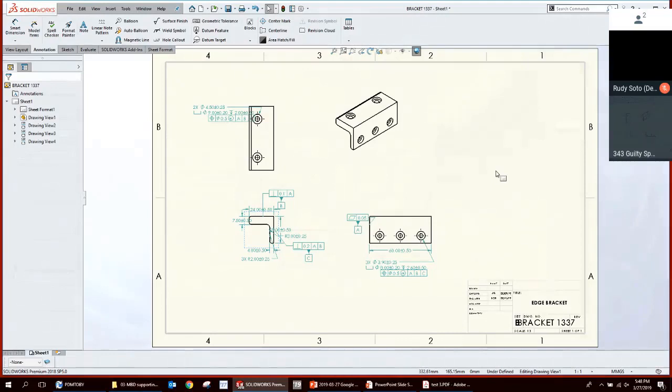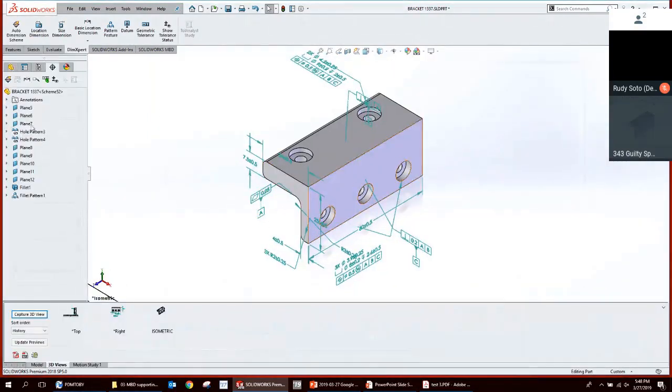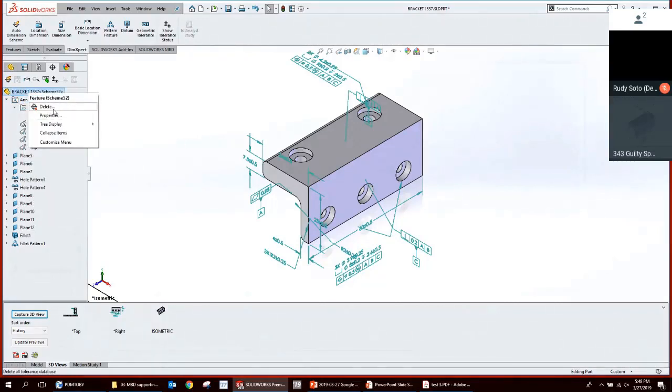There was just an option there for design annotations, not the other kind of dimension I was referring to. Yes. Can I pull in all feature tree dimensions? So it's a great question. Now that you understand how SolidWorks DimExpert creates these annotations, it automatically assigns the annotations to what's called an annotation view. And these annotation views control the hide show state of the dimensions, right? The same thing happens with your regular SolidWorks feature dimensions, or can happen.